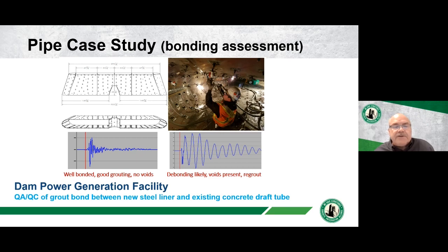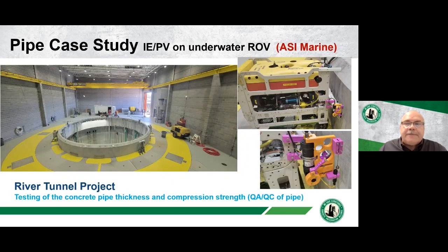If we got our signature amplitude on the left, that's a well bonded, good grouting job. If the amplitude opens up on the right, that had some voids present. That needed to be topped off a little bit more, so we were able to quantify that right on site.